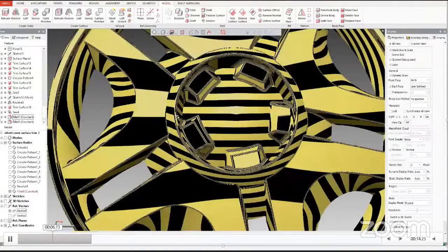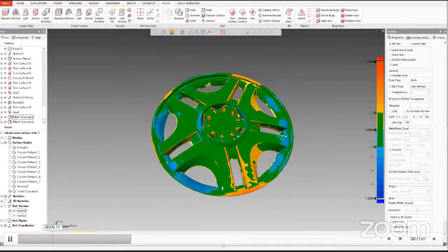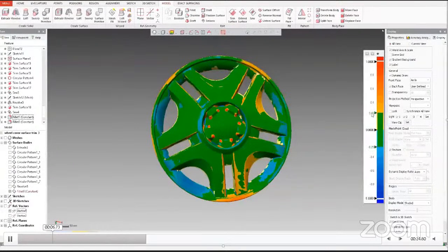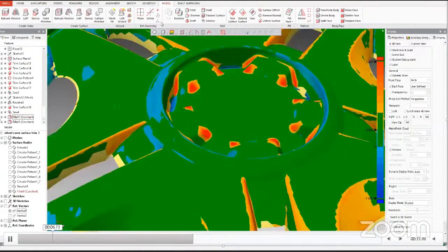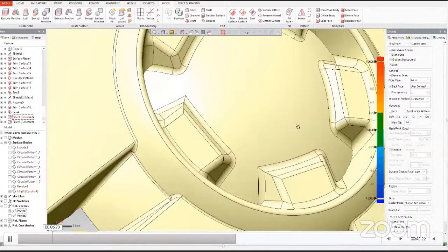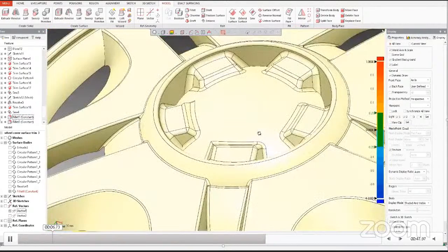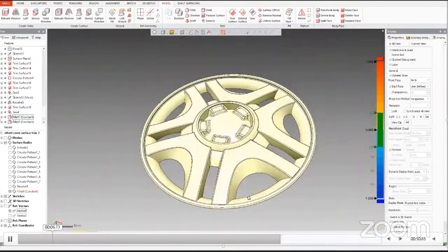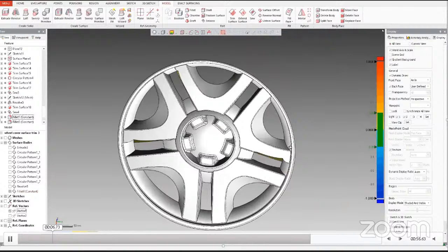And since these surfaces are not tangent to each other, we can see these strips, there is disconnectivity among each other, and we can also see the deviation analysis. We can see the green portion which has the accuracy of plus minus 25, and the small red region shows that the solid CAD model has deviated from the mesh data. So we can readjust the fillet size. These sizes might be bigger. That's why it's showing us the red regions. Sometimes we can compromise. Sometimes we have to remodify such small features.